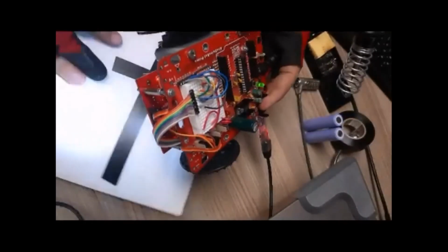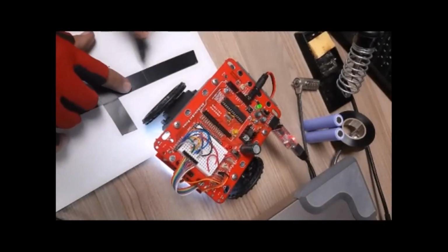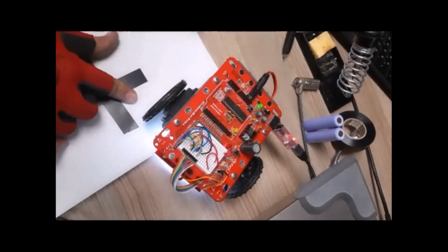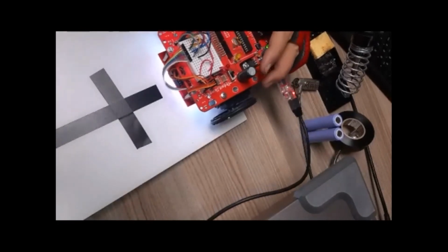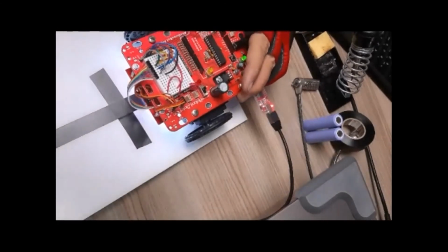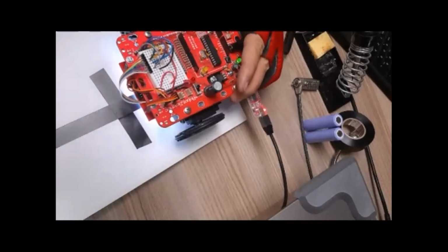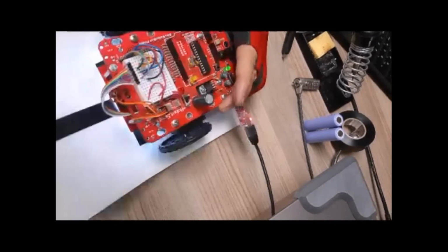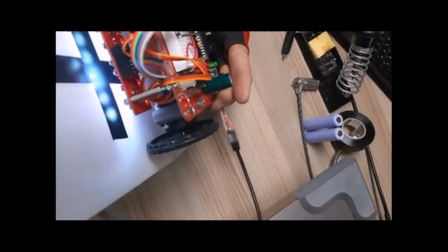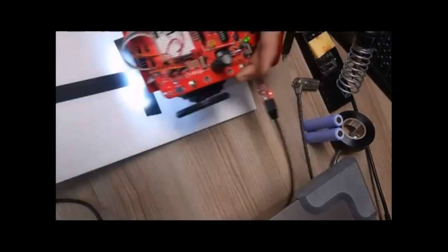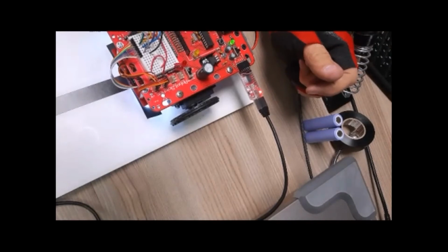So what we're going to do is have a look at what light values we get. I'm going to remove a piece of tape over here. Right, so we're going to have the robot in this position where all sensors are over white. Then we're going to have the robot over the line where just the middle sensors are over the black. And then we're going to have the robot over the line where all the sensors are in fact over the black, like that. And then we're going to look at the different values. So let's go back here and go in there.